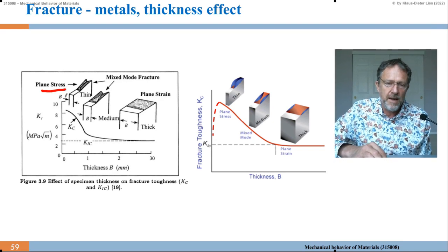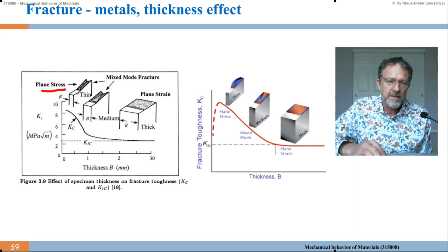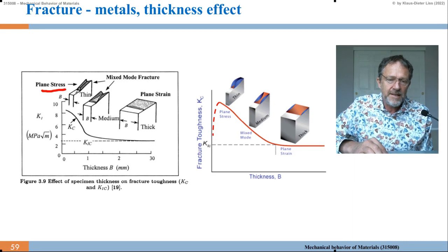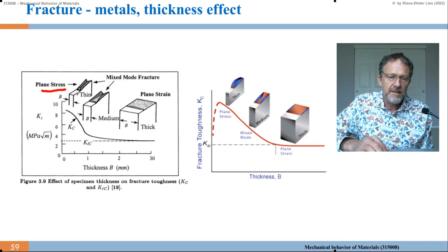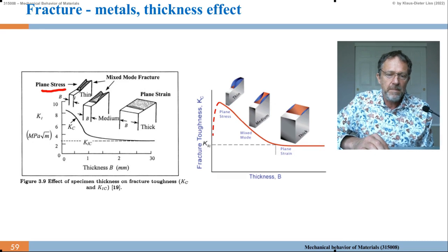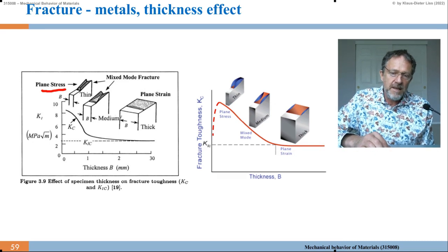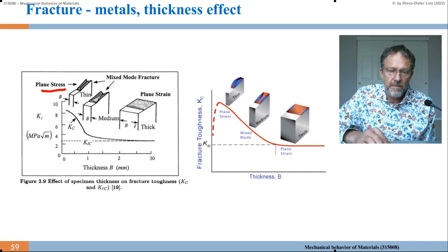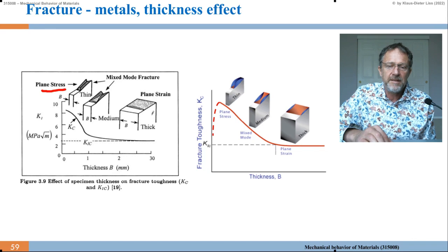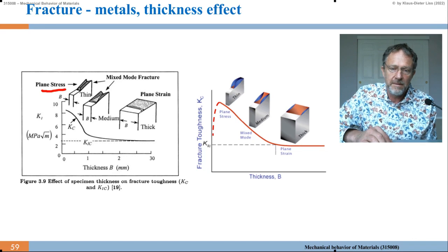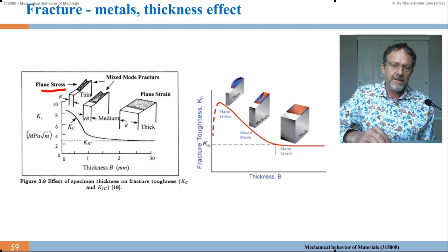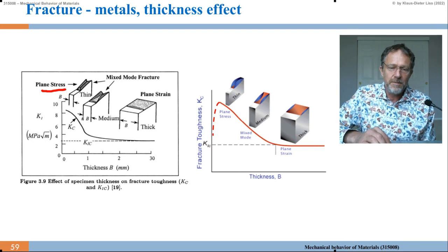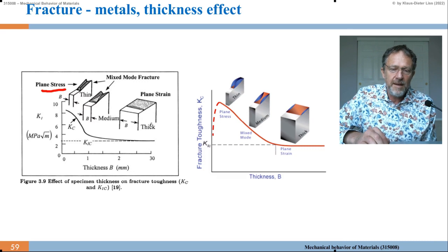Here we don't care about the thickness. The stresses are constant over the thickness B when B becomes very thin. And obviously, as B becomes thick, a meter thick or infinity, then we have the plane strain situation. And then, of course, there's a transition zone between very thin and very thick, and that we call medium.